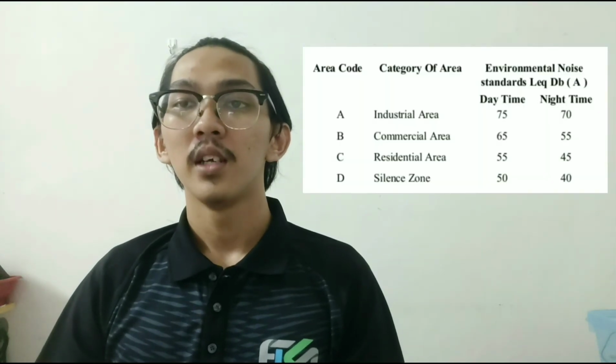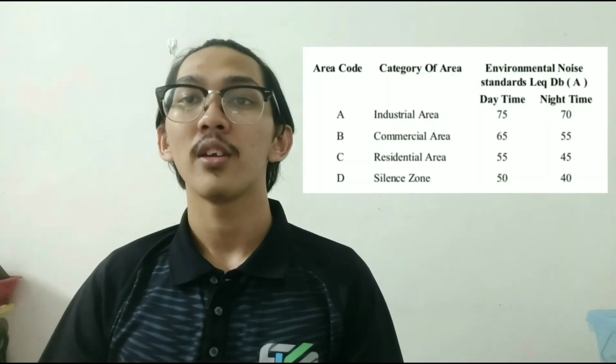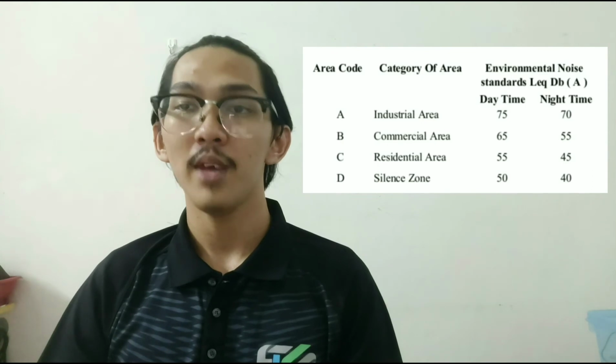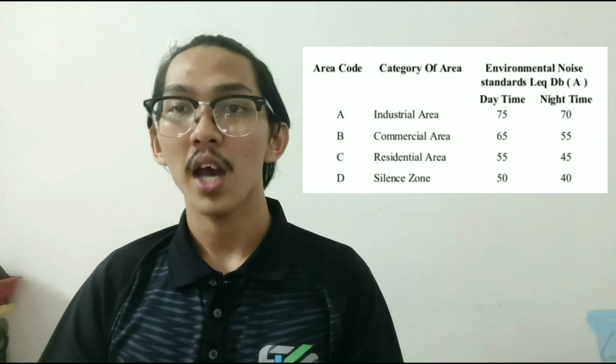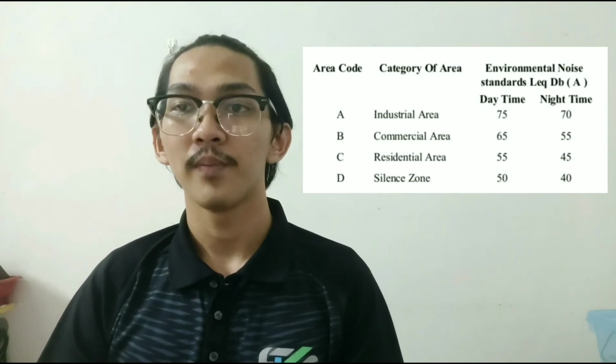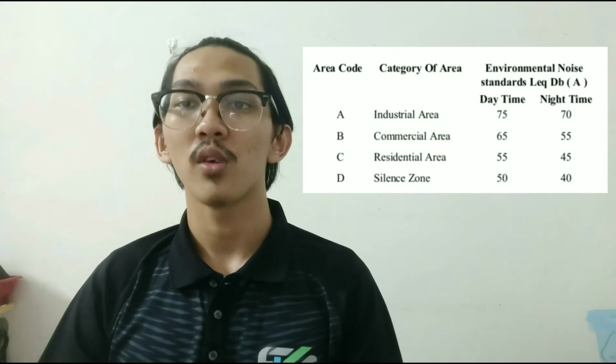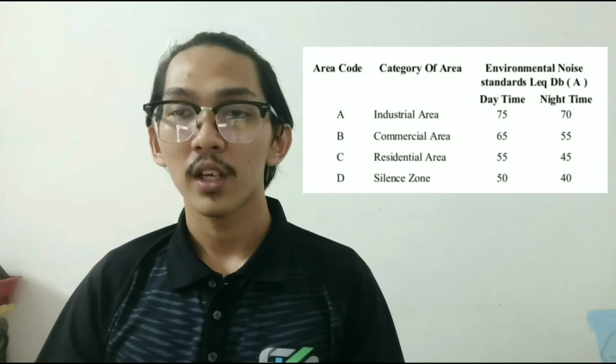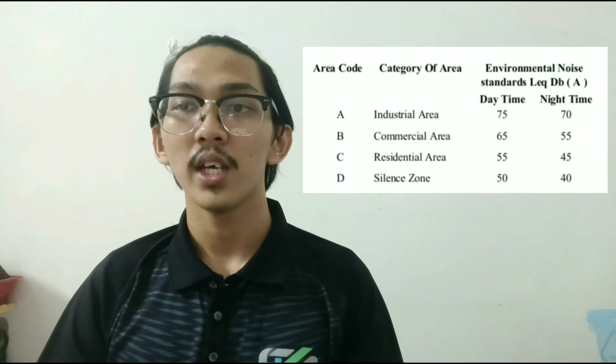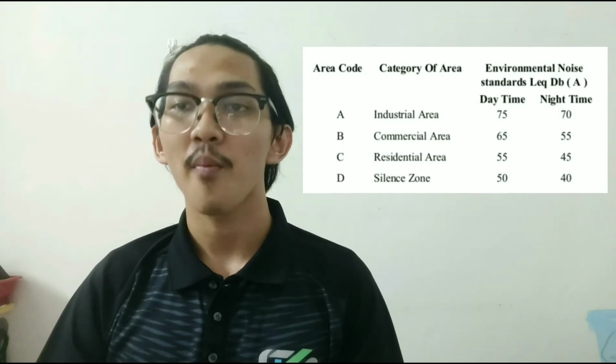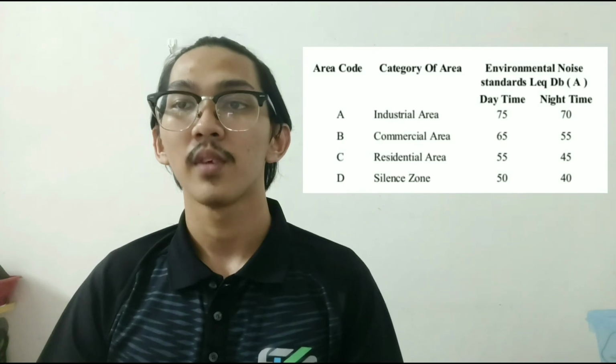According to the table, the noise level exceeded the required noise level standard, which is 55 dBA. The recorded data was quite high because the road was busy during peak hour, which led to the source of the noise pollution. The vehicle noise may cause disturbance to the students as it will affect their study, their productivity, and can cause stress. While conducting the experiment, we took precautionary measures to avoid causing error to the data. We need to remain silent when using the noise level instrument as the instrument is very sensitive to sound.